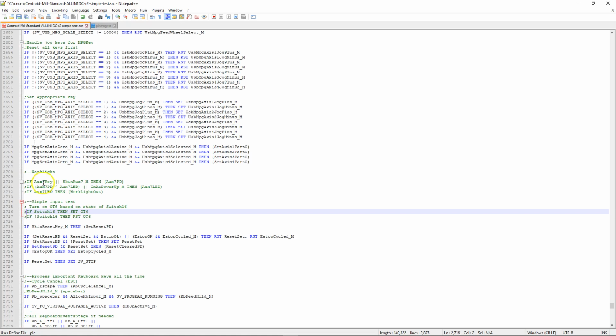Okay. I'm going to save this, and I'm going to recompile. Now, you might be asking yourself, well, hey, it won't compile because there's nothing that's actually doing or setting anything with the OT6 because I have it defined. Well, just because it's defined, if there isn't any logic in there, it'll still compile. The only time it will gawk at you or fail on you is if you have something set on here, but then that is not being defined in your statements.